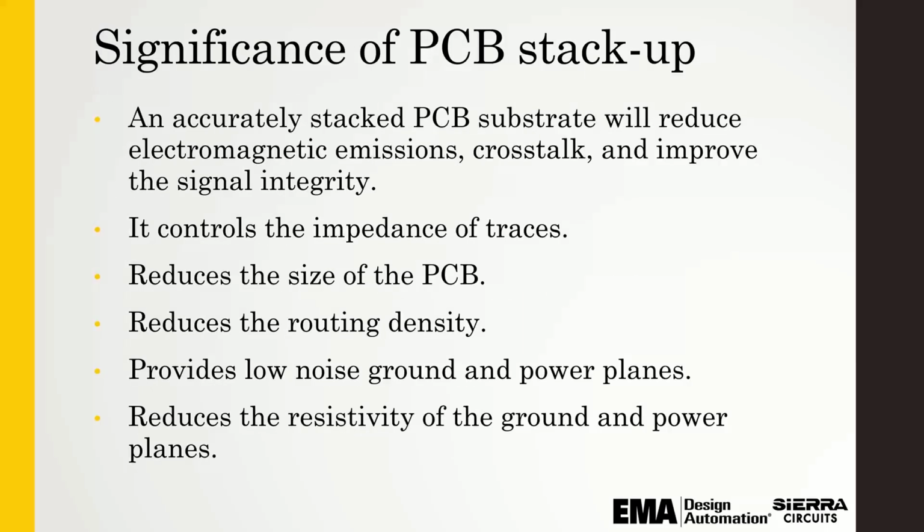Lastly, you want to consider how many ground and power layers you have. The use of ground and power planes allows the designer to allocate signal layers purely for signal routing, which can reduce the DC resistance in the power and ground rails. This would ensure less DC voltage drop in the devices. So there are some advantages to taking that strategy in your layout and your stack up. A couple more points on the ground layer. That's obviously where you're going to connect your power supplies, and the power supply is a flat plane of copper, usually in the PCB, connected to the power supply rail.